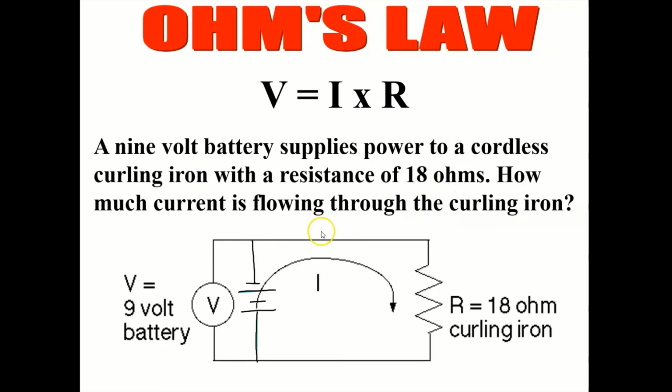If I put what's called an ammeter right here that measures current, A right here, it would say we have 0.5 amps of current. That's I. Simply using Ohm's law becomes more useful when we have a more complex circuit.